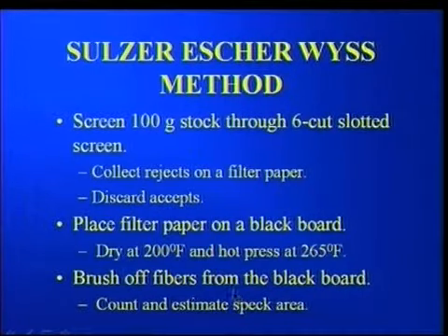The Sulzer-Escher-Wyss method involves again the same step, going through a 100-gram stock screening process, and we collect the screen rejects on a filter paper. We place this filter paper on a black board and dry it at 200 degrees Fahrenheit and hot press it at 265 degrees Fahrenheit.